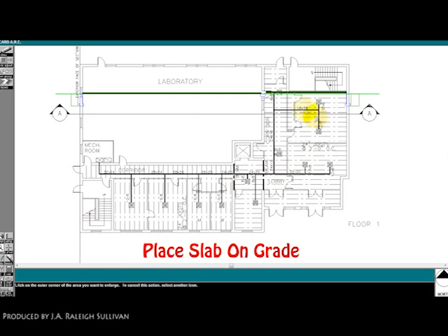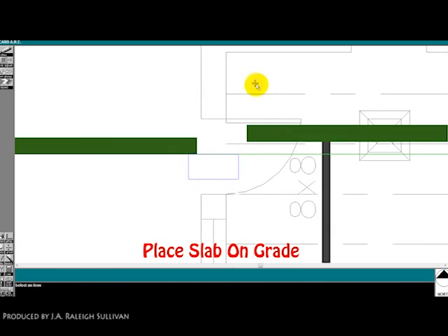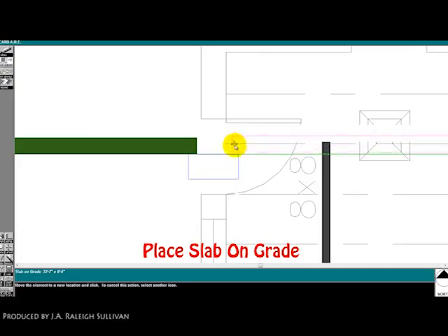Also, the slab is broken here at the internal footing. This is because the bearing wall should rest directly on the footing and not on the slab.